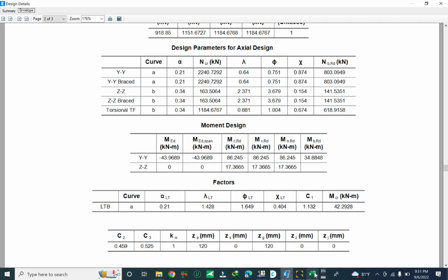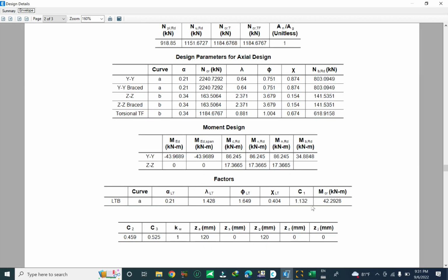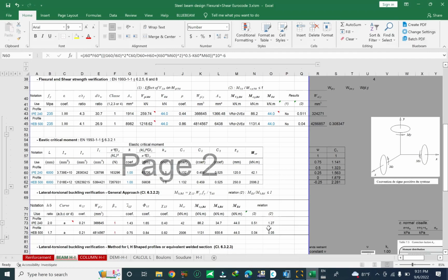32.29. So in ETABS, when you change the support condition, the parameter inside the beam is not changed. This is a big issue, a serious issue when you design to the Eurocode based on the ETABS software or CSI product. You have to check it again and again, and it's very concerning when you design with the software. You have to make sure you can verify it and know why it's different. You see here the parameter C1 is for the simply supported with distributed load, and ZG 120 is correct.